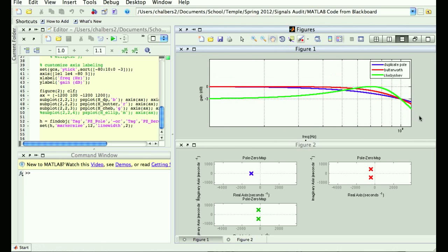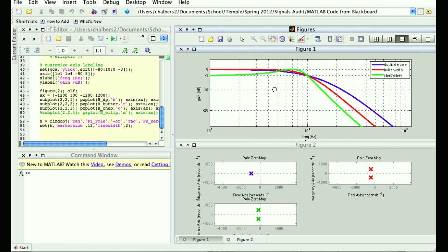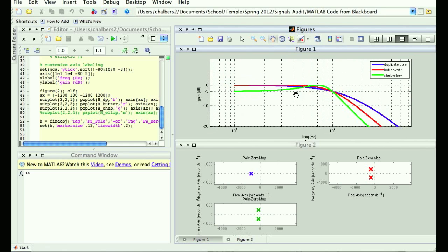I really don't want to get into the specifics of this. We could do a month on this, and we're not going to. I just want you to get it, to put that seed of curiosity in the back of your mind. There are all these cool trade-offs you can make when you do filter design. One trade-off is you say, okay, for my pass band, I'm willing to let my signal get no smaller than negative 3 dB. That means 0.707. As long as my signal doesn't get any smaller than negative 3 dB, I'm willing to say that's acceptable for pass band behavior.